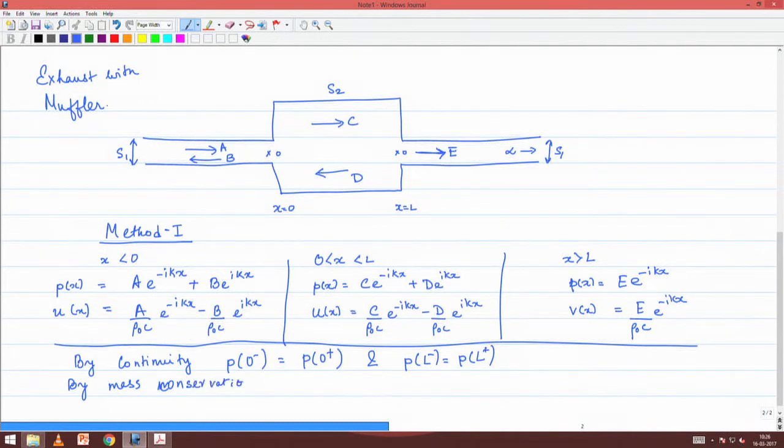we should have the density is anyway same for the fluid throughout. So, essentially the mass flow is given by density times area times velocity, but the density part is anyway same, so no need to account for that. We will account for only the volume velocity. Volume velocity is area times the particle velocity, but the area is changing. That is why I said the area change will create a new problem for us. This is what is showing up.